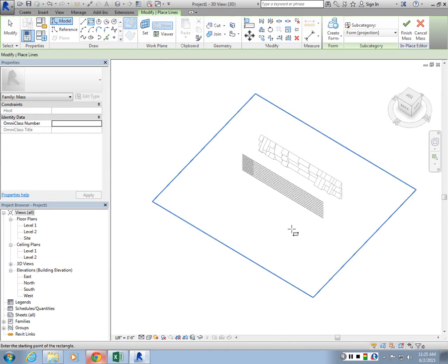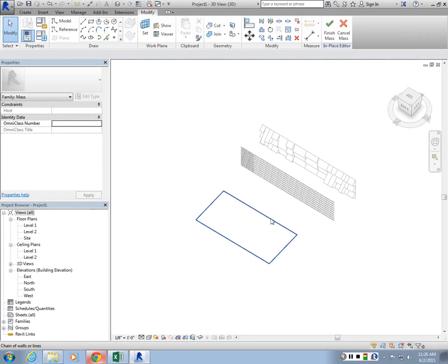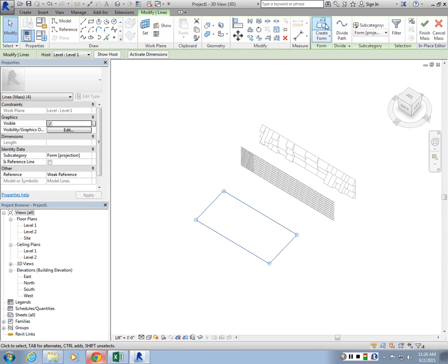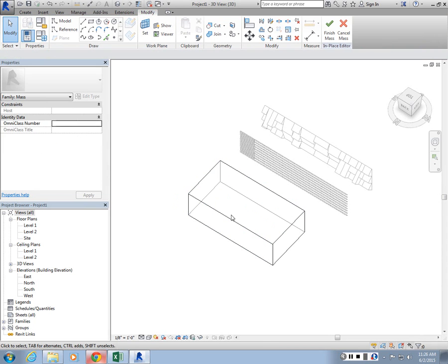Now, when you're in the massing tool, this enables you to play with volumes, model a form, and extract the surfaces of it to be used for the project. I will start with something simple. Let's create an extrusion. I'm going to create a rectangle. If you want to turn it into a three-dimensional form, choose the profile and then go to Create Form. Create Form looks at the profile and turns it into a three-dimensional or two-dimensional form. In this case it can extrude the rectangle.